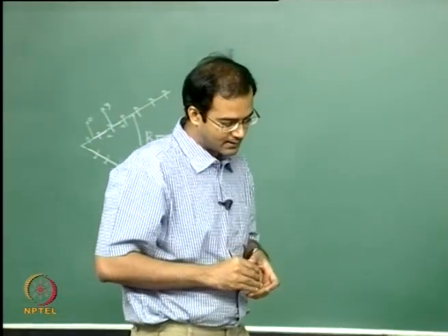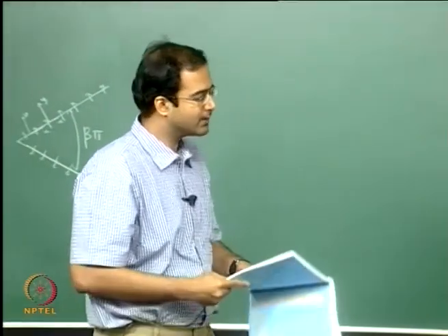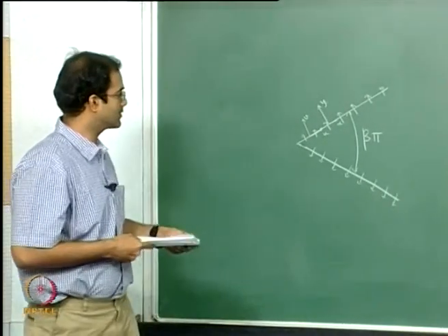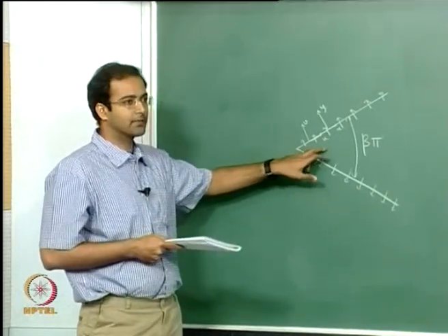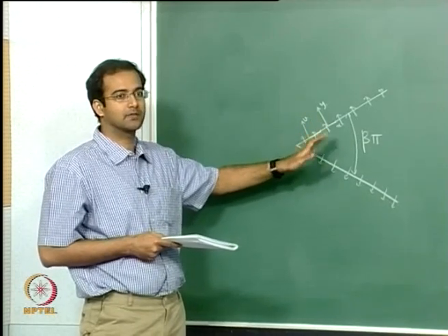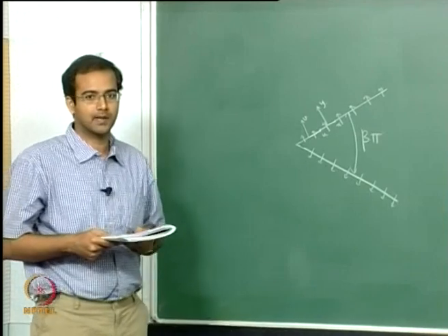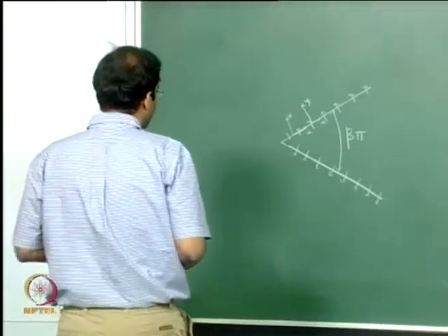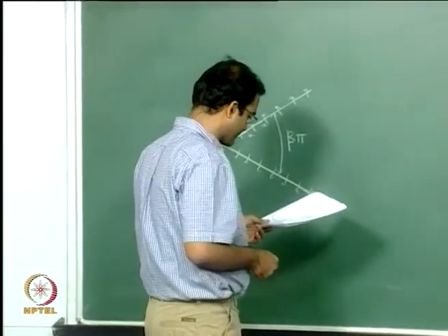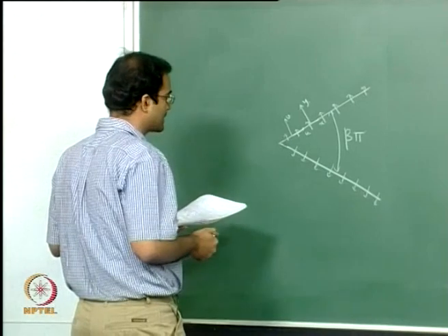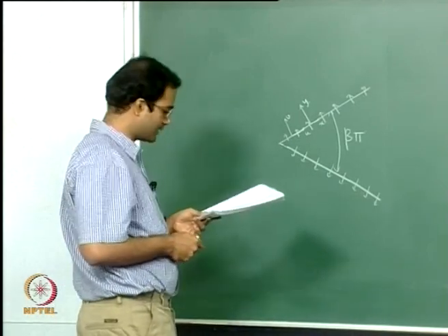We will consider the similarity solution for that today, and in fact this will be the most generic case, and you can also apply the case that we derived before where there is no vertical velocity, and that gives you the solution we derived in the last class. For this particular case we will look at only the flat plate, but it does not matter, we will apply the general Falkner-Skan solution applicable to many configurations.